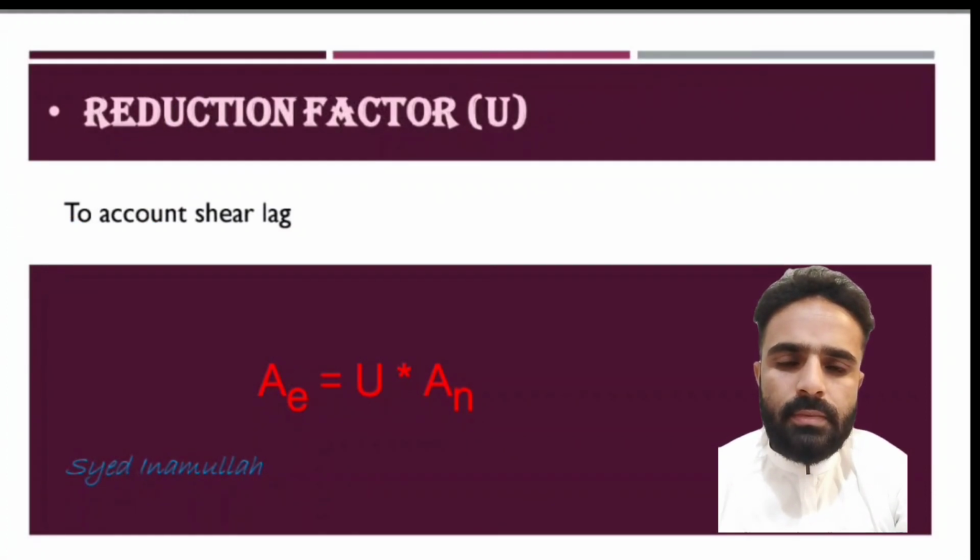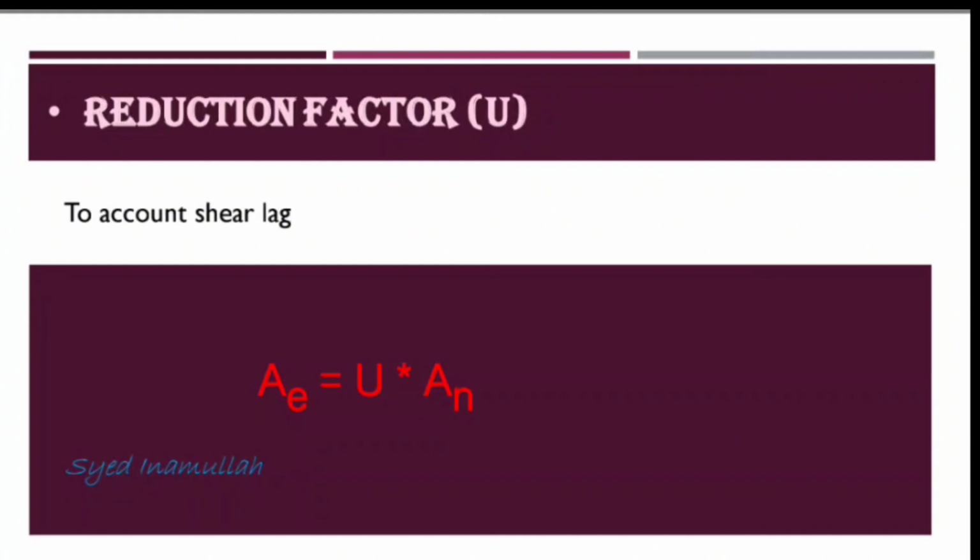Let's dive in and explore the fascinating world of shear lag reduction factor. The shear lag factor is a critical concept that helps us account for uneven stress distribution in connected members. By understanding the reduction factor, we can design safer and more efficient structures. When uneven stress occurs in the members, then we minimize the net area by a reduction factor.